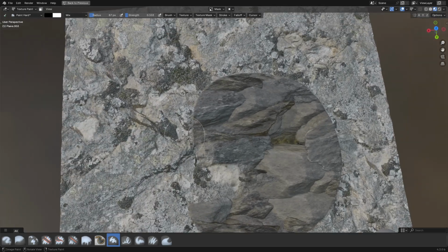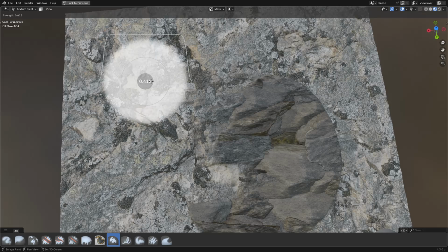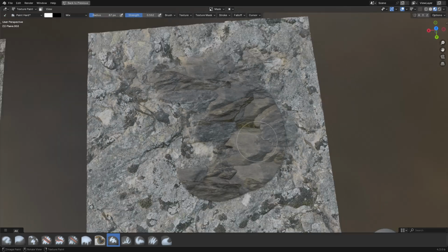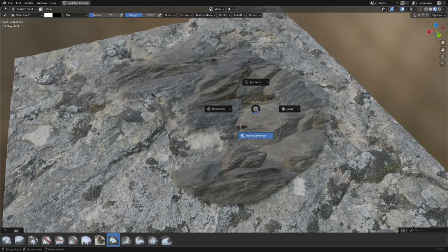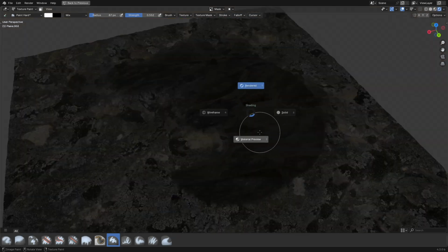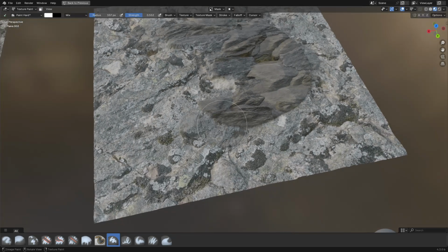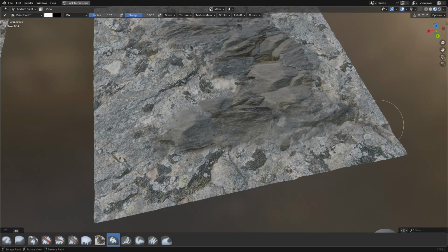All right, we can use a grungy texture mask as well up here if we wanted to set that up to go ahead and make them blend a little bit differently, perhaps with some noise in it and stuff like that, right? Use it as an alpha, basically. Let's get something a little bit more dramatic going first. Also, I found that doing this in material or rendered preview, it does tend to have some little hiccups with lighting sometimes. You have to get out of texture paint and mess around with it.